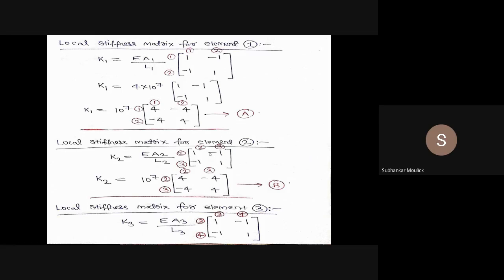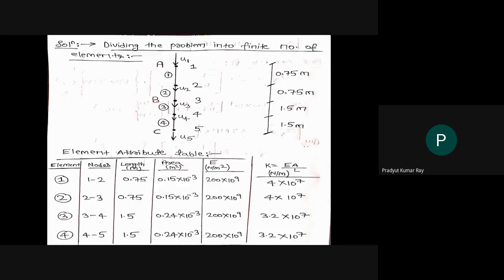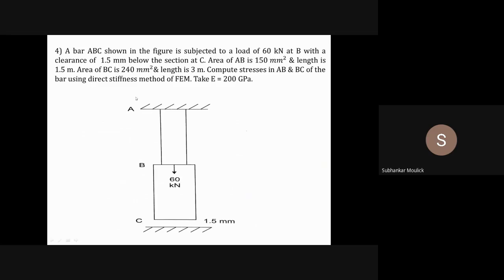Can you repeat this thing in 1 second? Yes, since I am using direct stiffness method, I have told these things earlier also. In direct stiffness method, the governing equation is nothing but the restoring force equation that we get from a spring, that is F is equal to minus kx. Normally we exclude the minus term, so F is equal to K into X. F is the force acting on the element, K is the stiffness matrix of the element, and X is the displacement of the node.